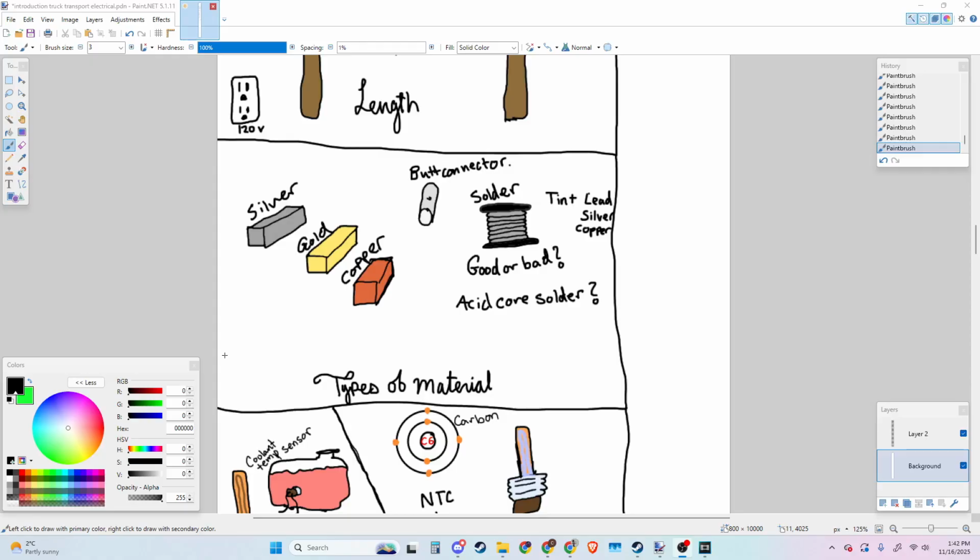I would advise butt connectors, as you can see here in this picture, these little metal tin butt connectors. I would advise butt connectors on most of your applications, but when it comes down to if solder is actually bad, I wouldn't say solder is bad. Another problem with solder is the person using it. Using acid core solder is only for plumbing and metalwork. It has no place for wiring as it causes copper deterioration. Another thing to keep in mind, if you overheat copper, it oxidizes. When copper gets oxidized, it corrodes. So if you're using solder, be careful not to overheat the copper.